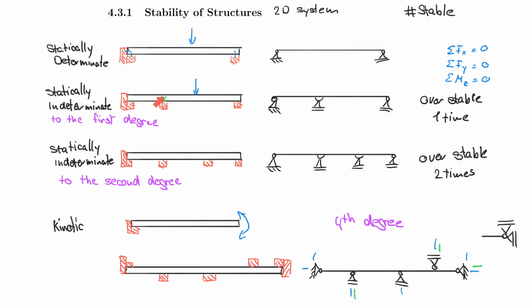But if you were able to calculate how much this deflects downwards, if the support is not there, then you can use the boundary condition of the support, which says, hey, the deflection here must go back to zero because the support does not allow this to go down, so that you can actually calculate how strong the support has to be to bring it back into the zero position. And you can do this multiple times. This is conceptually how that would work.